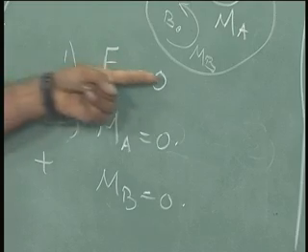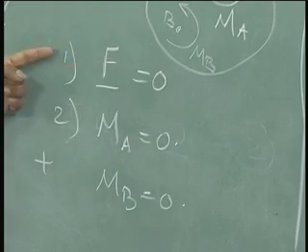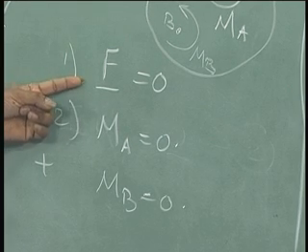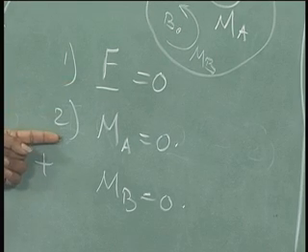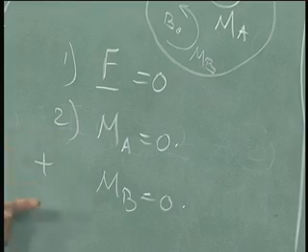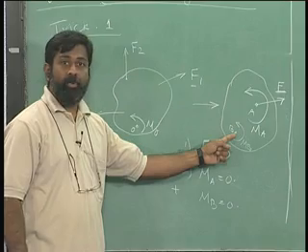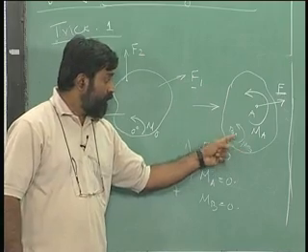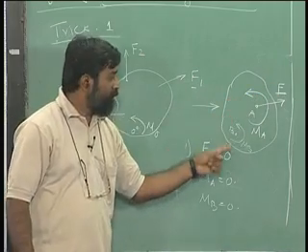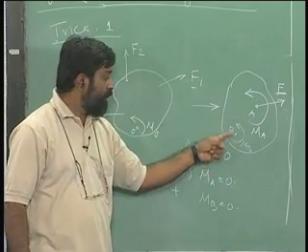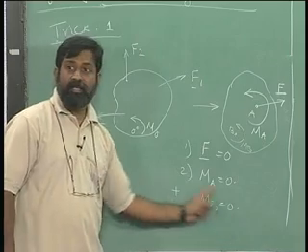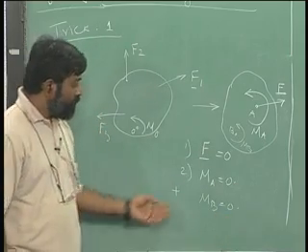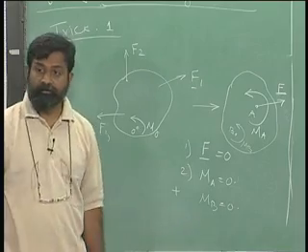Remember, there are two equations that I can find from here, which is x component and y component of resultant force equal to 0, and Ma equal to 0. Supposing I say, I am going to take another point here, I know that this point is also stationary and therefore the resultant force is going to be the same, but moment will be different, Mb, and can I add that and say I have the fourth equation? Can I do this? That is the question.